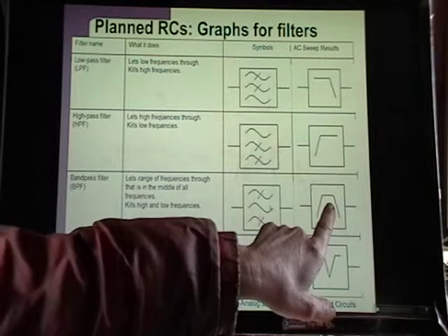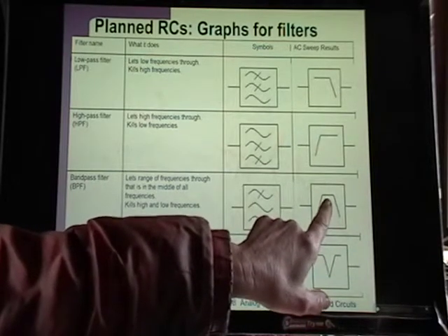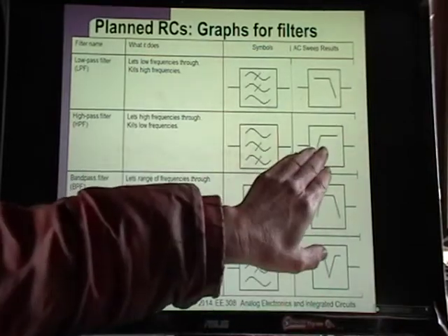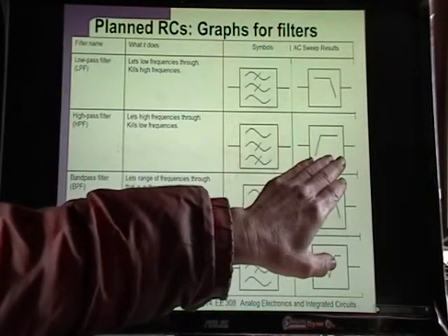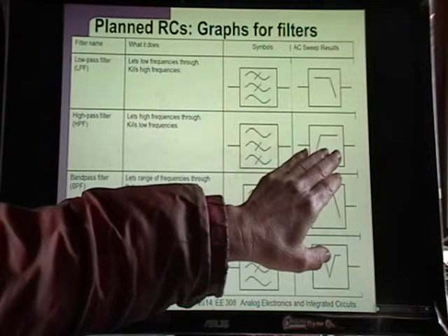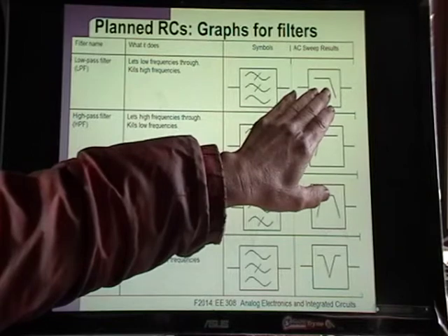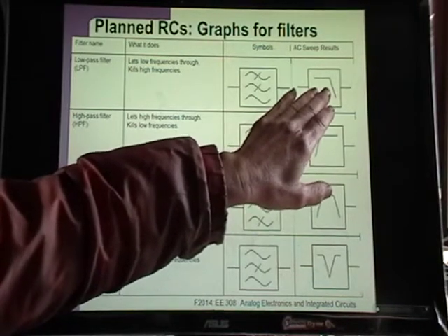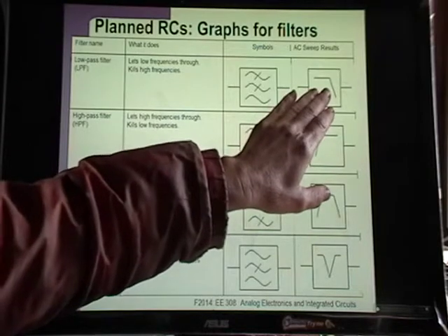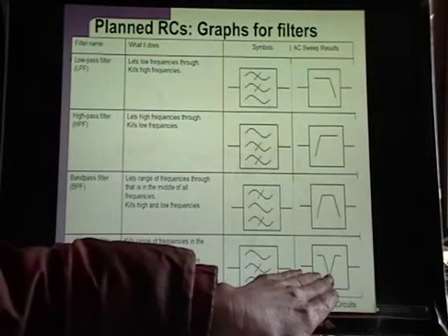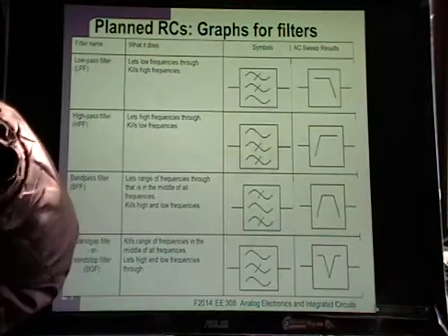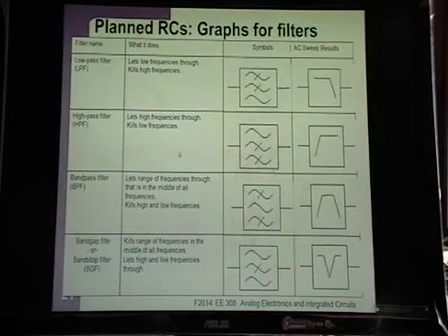Okay, and this is for a radio. When you turn on to a particular station, it needs to get a particular frequency, so this just picks out that particular frequency. High-pass filter, there's a number of reasons for this. I'm not thinking of a good example right here. Low-pass filter, noise, there's two types of noise that are most common. One's a high-frequency noise, and one's a 60 hertz noise. So you can get rid of the 60 hertz noise with this, but this right here, if you cut out the high frequencies, you get rid of a lot of noise. Okay.